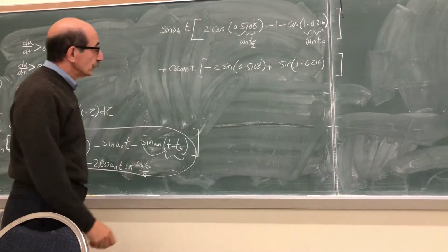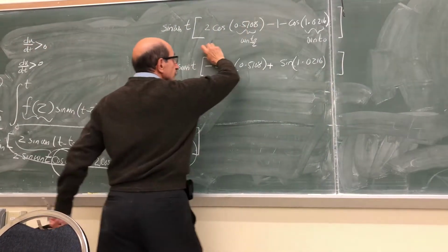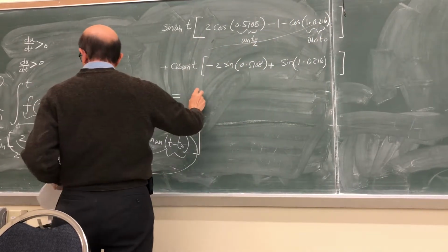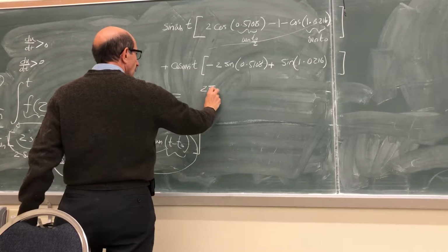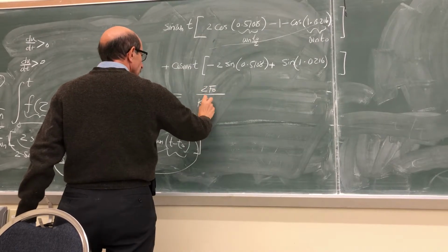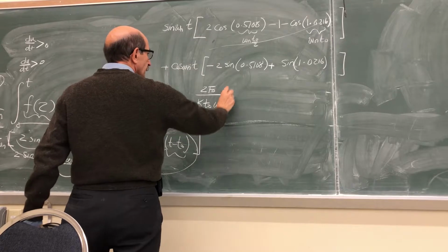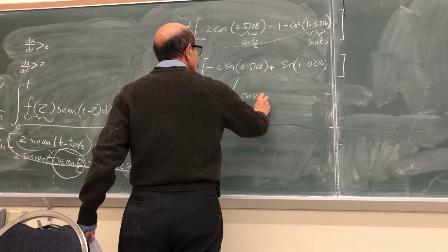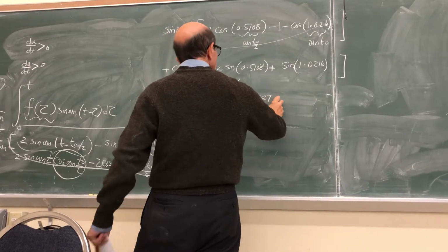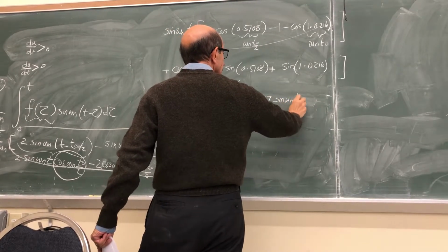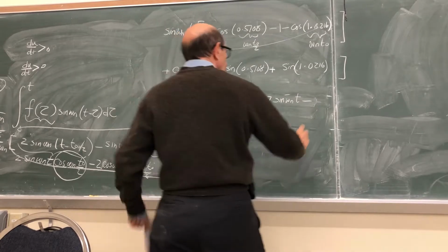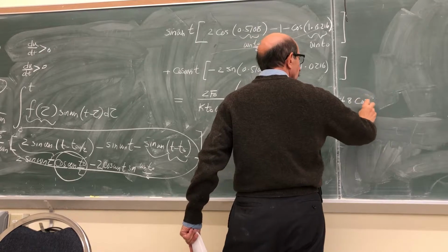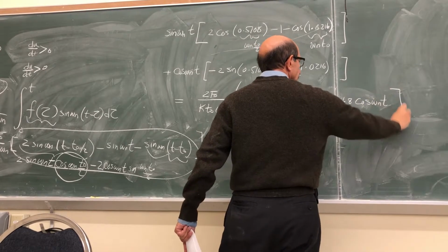So, in other words, if you do these calculations and simplify this, you basically will get 2f0 over k t naught omega n times 0.2227 sine omega n t minus 0.1248 cosine omega n t.